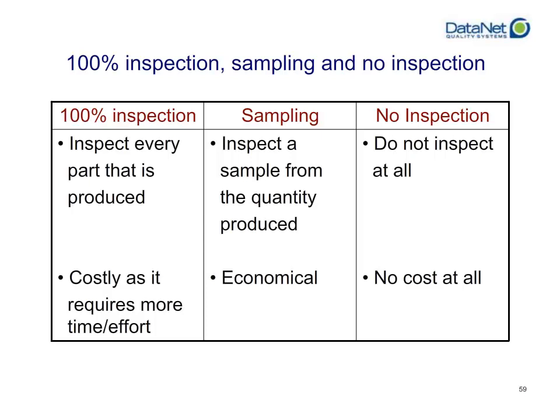Now, there's the question about, well, if I'm sampling, how can I know if everything that I produce that I have not actually sampled, if I'm not doing 100% inspection, is still under control or in tolerance? And we're using statistics, and we're using the nature of the fact that we're going to talk later about the bell curve and whether or not we're actually able to produce things repeatably. But for right now, sampling is going to allow us, with statistical certainty, depending on how often you take your readings, to show if it is likely or not that something is changing.